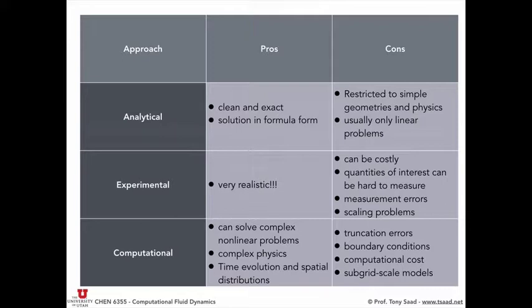But numerical methods or computing, CFD, suffers from other things. There's modeling errors, there's truncation errors, there's stability issues. You may not be converging to the correct solution. We'll touch on all of these. You may be simulating the wrong thing, and we'll see. All of those come from the fact that we are going to approximate the true governing equations using discrete numbers.